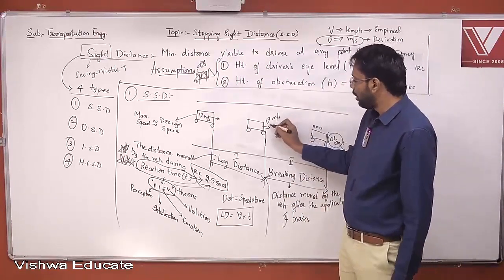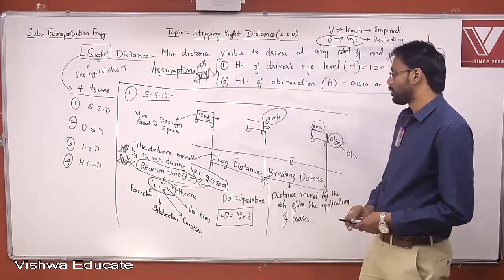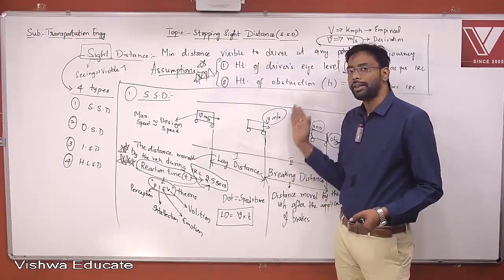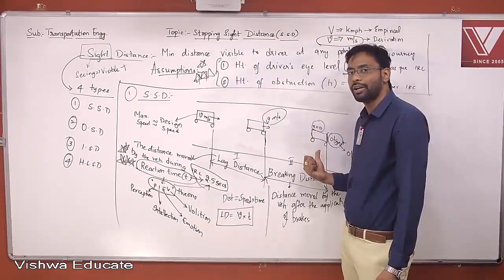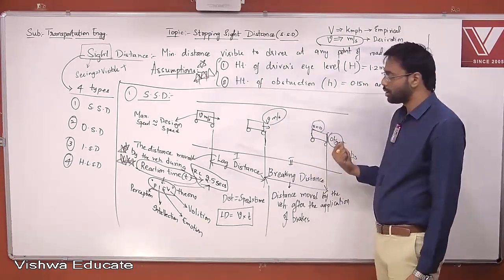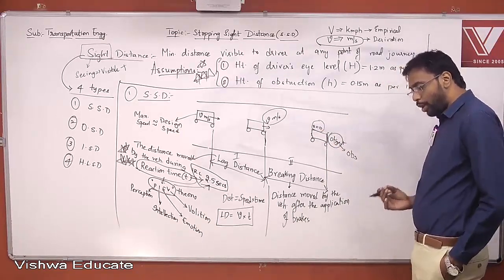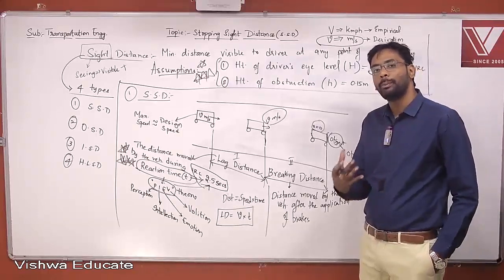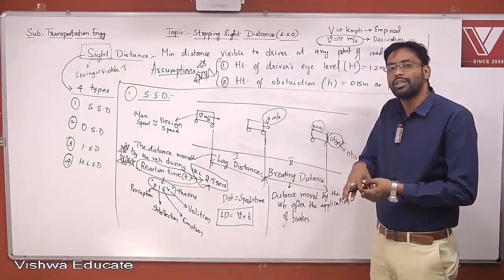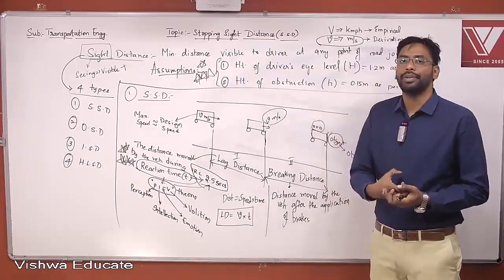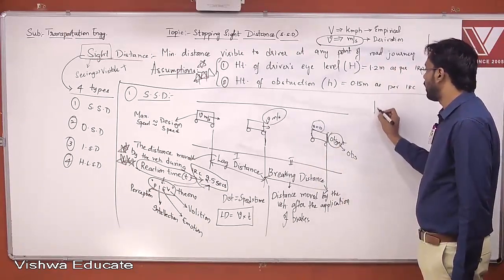Now this is important for us when we are solving some problems. So before applying brake, at that point, velocity is the same as design speed, and after application of brake, at the end when it got stopped, obviously the final velocity is 0. Now, what comes into picture when you apply a brake? Obviously, if you apply a brake, the force which is helping the vehicle to stop is frictional force, right? So let me consider this vehicle here.